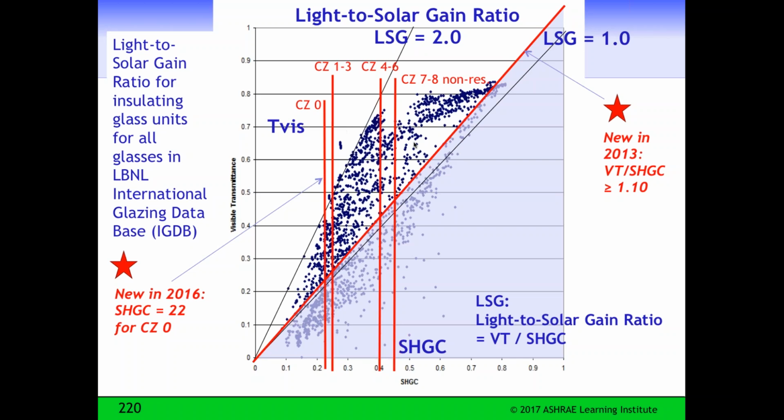But in some of the simulations that I've done, you can have a major impact on energy efficiency improvement by judiciously selecting the combination of solar heat gain coefficient, the SHGC, the U-value, and the visible transmittance: high visible transmittance for daylighting, as low as possible SHGC in most locations, and a U-factor that is appropriate for the climate. It can be a major determinant of the effectiveness of the envelope.